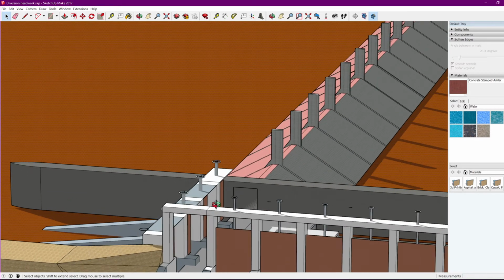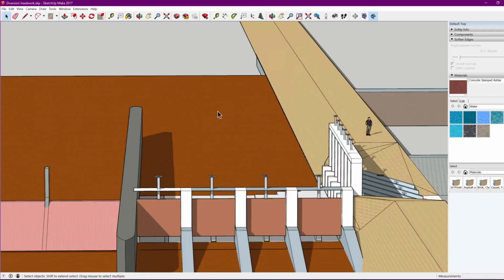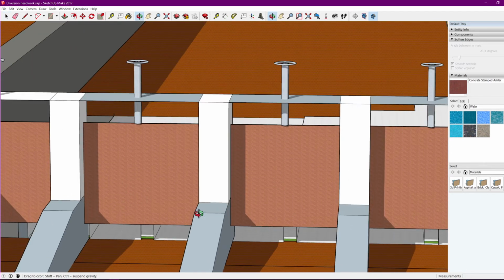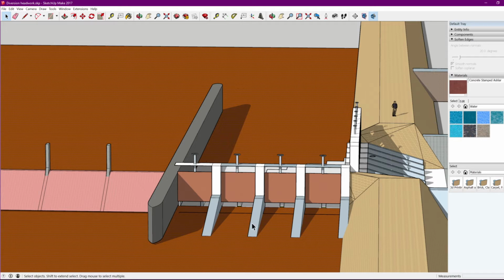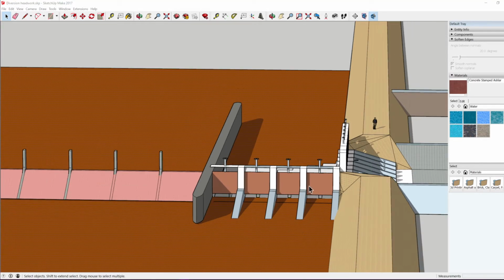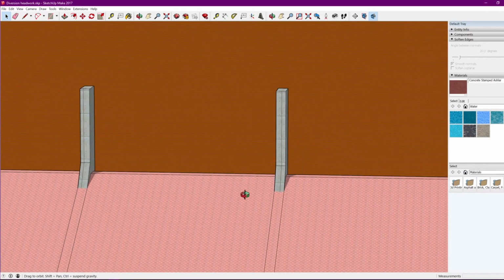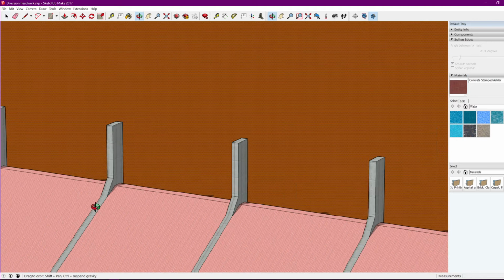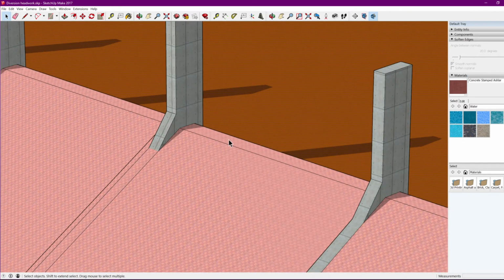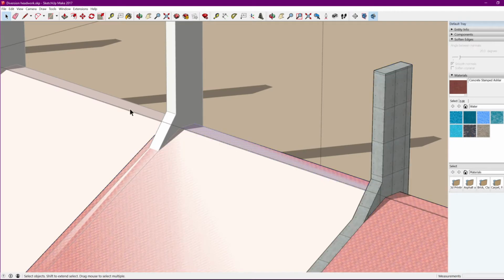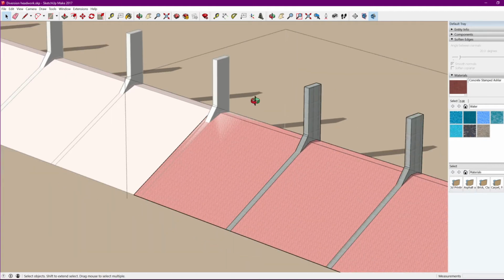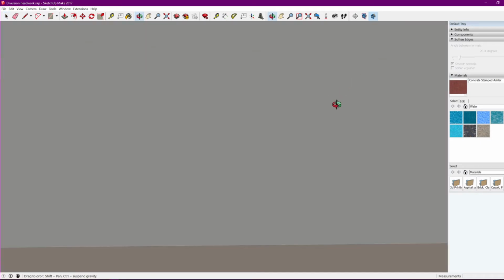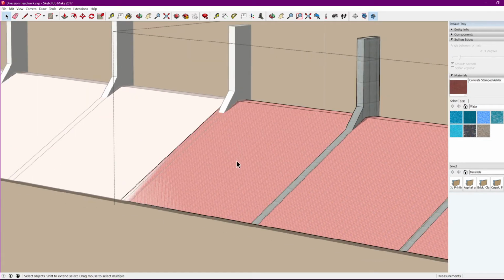Under normal conditions, we have these extra gates on one side of the weir so that some water can be released to the downstream, and only in the case of high flood seasons, the water will actually flow over the weirs. Now the barrage is similar, but the height of the barrage will be much smaller. That is, the fixed height at least will be smaller. I'm not sure if it can be modified in this model, but anyway, you can understand that whatever height is provided in this weir, the height of the barrage will be smaller or almost negligible.